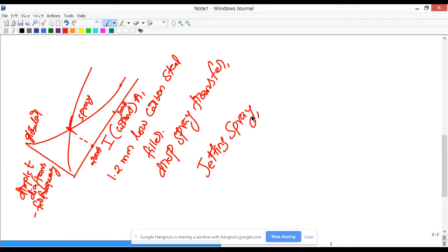in the arc. So the plasma pressure inside the arc, the Lorentz force increased by the increasing current, and the magnetic field generated in the droplet would all lead to deflection of the droplet, and in some cases it may also lead to explosion of the droplet that is detached at higher amperage. If you reach such a state where the Lorentz force and the magnetic field generated are so high, and the pressure inside the droplet can lead to the explosion of the droplet, and that is what is known as spatter. Okay.